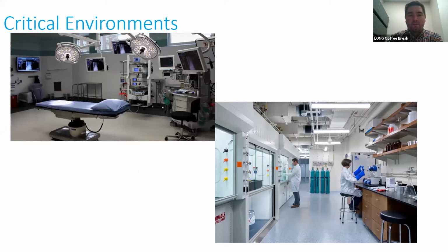Really, you have two different things going on there. With the positive pressure room, you're trying to keep out any bacteria, germs, anything that's going to work its way into that room. I think of an operating room with someone on the table, they're getting their knee worked on, they're cut open. The last thing you want is something to infiltrate that room and potentially get that patient sick. So that's why you have that positive pressure.